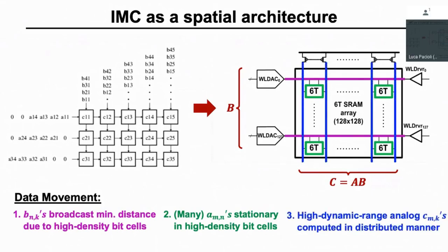The other operand, in this case, is going to be, in fact, a high dimensionality number, right? This accumulation, say, across the row of a matrix. But what's interesting here is that that high dimensionality number is computed in a distributed way. This could be, for example, an 11-bit, 16-bit, 32-bit number, whatever you think it could be, depending on the dimensionality of your matrix. But here, that number is computed in a distributed way. So in fact, we don't incur that communication cost. This is precisely that amortization that I was showing on the previous slide.